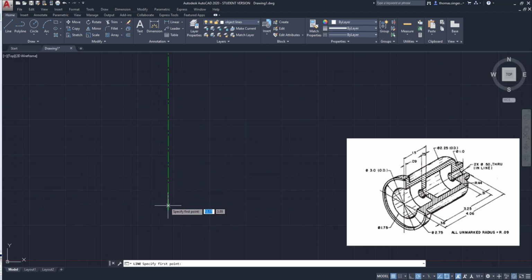We're going to start near the bottom of the object, picking the starting point as the center point, and work to one side. Coming off to the right-hand side at the bottom of the object, you'll see that we've got a 1-inch diameter shape. So that's going to be a 1/2 inch. All the diameter dimensions that we work with are going to be half the size as we continue to build this out. So it's going to be 0.5 as a linear dimension.